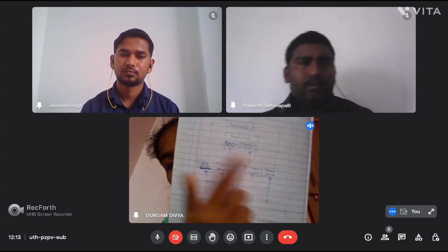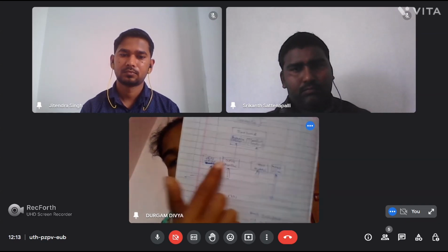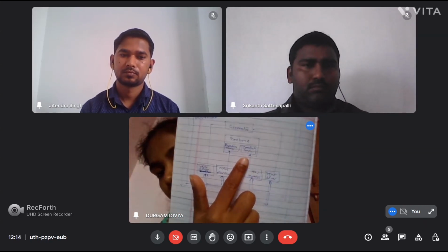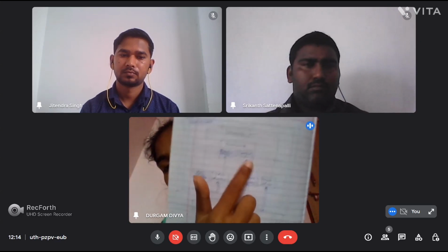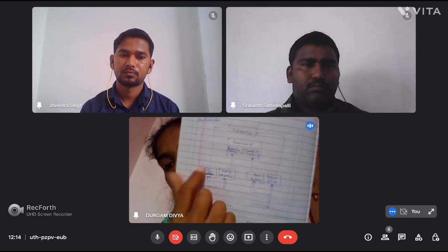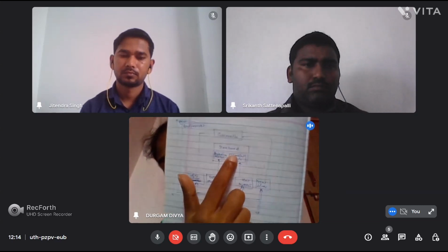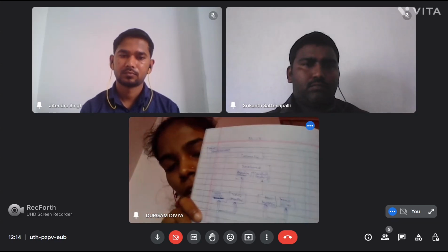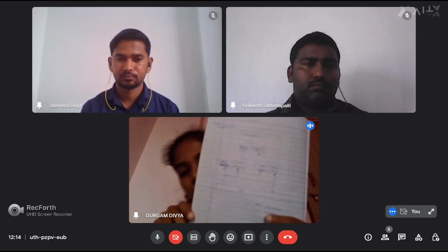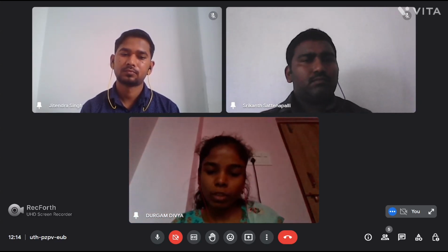You can take any project. So this is the function of the scoreboard. It will compare the reference model output and the expected output, and give the appropriate output. In the scoreboard, it compares the output from the reference model, and in the combinational logic the output comes from the read monitor. Here it compares and gives the appropriate output. That's about the SVTB architecture.